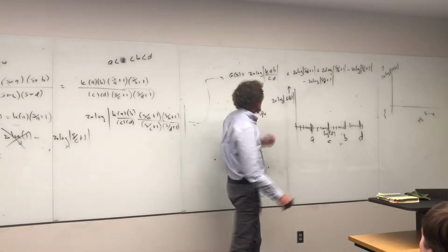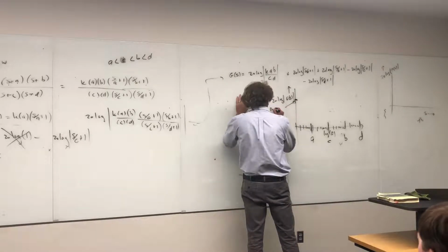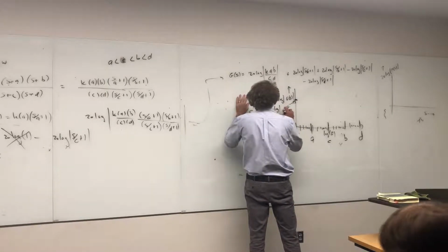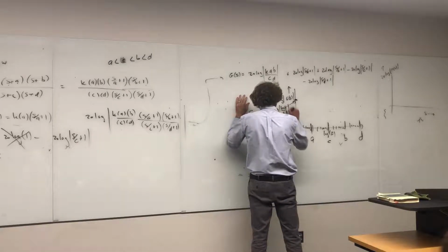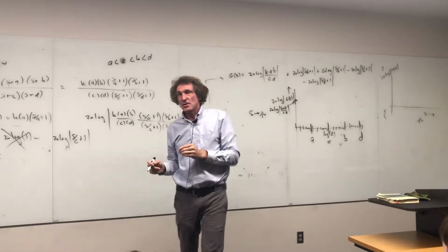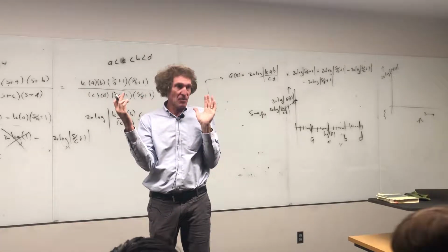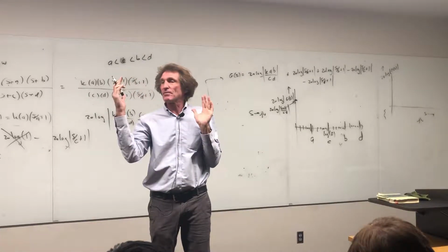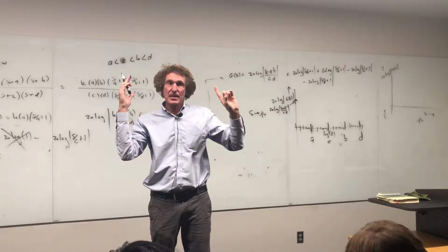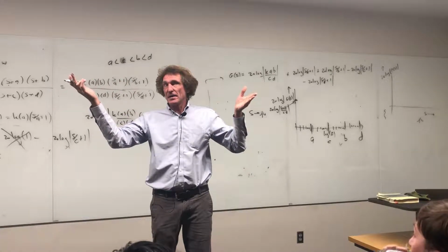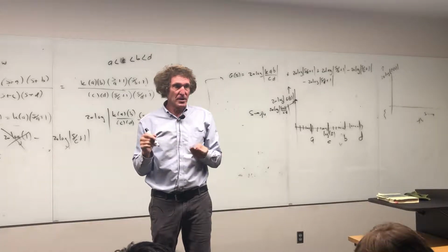Follow me? Here, you know you're going to start at, this point is going to be 20 times the log of the magnitude of KAB over CD. And really what I'm trying to say is it's going to be 20 times the log of all the constants after you strip them out from that S, all the functions. You want to always have S over something plus 1. Remember that. Always S over something. Sometimes people forget that. They leave it as S plus 1, and then they don't pull out those constants, so they get the wrong scale. That's what I'm trying to warn you against.